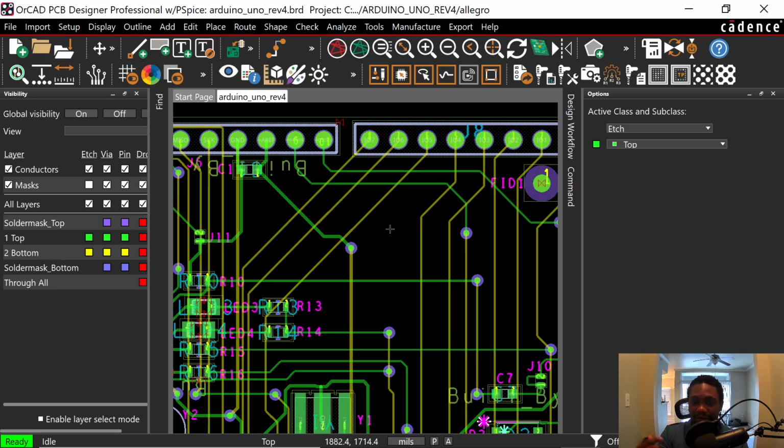Okay, the benefit of the Constraint Manager is to help you design by the rules set by multiple people and multiple stakeholders in the PCB design process, including your manufacturer, so that by the time you submit your printed circuit board design, you don't get a bunch of issues back. And by the time you get it fabricated and made and in your hand, you don't have more issues that could have just been solved if you had moved something closer to the other thing or moved something further apart from the other thing usually. So that's the general purpose of Constraint Manager.